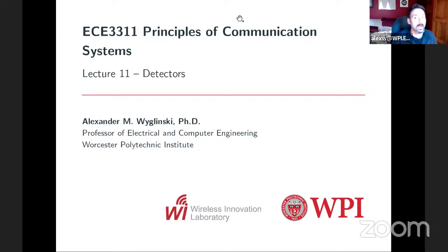We're going to look at how the receiver detects the correct point at which to take that value. It's relatively complicated because, as opposed to baseband communications, now we have passband communications. First of all, we take it to a carrier frequency, so we need to figure out how to bring it down to baseband, and then where to sample that information. That's the purpose of this lecture.